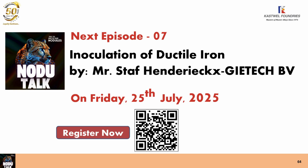The third thing is, please go in your foundry and have a look at it. Never pour with the ladle 50 centimeters above the mold. It should be 10 centimeters for a small mold to maximum 30 centimeters for a very big mold, because there you make turbulence, you make contact with the air again, and contact with the air in ductile iron makes dross. And the higher you go, the more the risk is that you have dross.